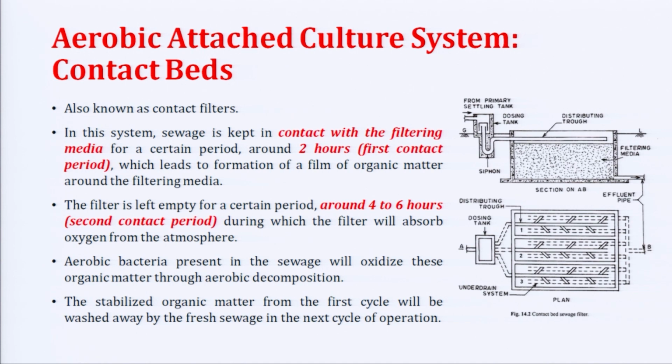They are also known as contact filters or contact beds. It is actually very simple. It is similar to a trickling filter, but here you generally do not trickle. Like in a trickling filter, you are trickling the wastewater, right. In this you do not trickle, you simply collect the wastewater, keep it in the filtering media and then let it go, keep that filter media empty for a period of time and then again you put in new influent.